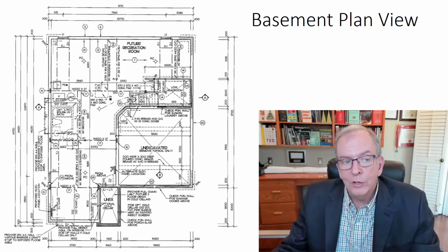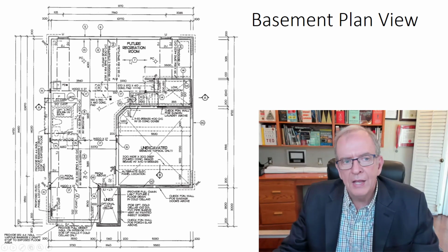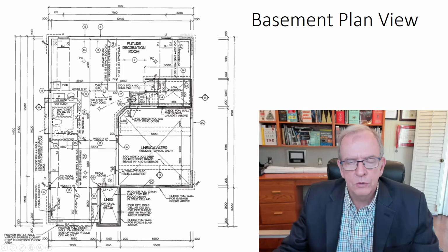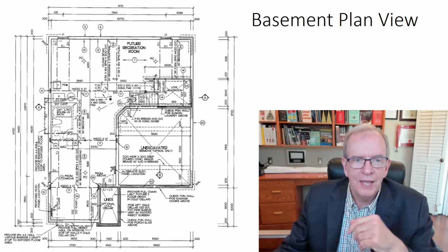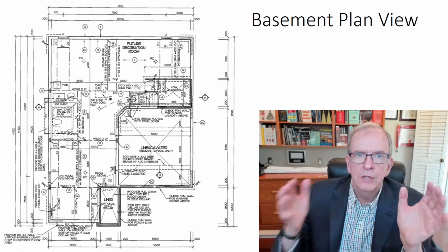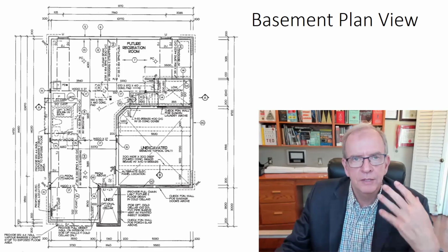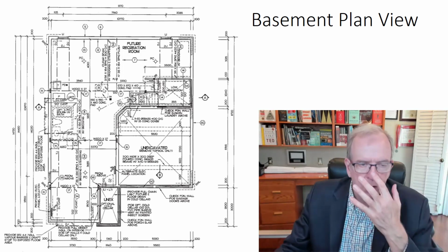More than likely, if you're looking at other drawings, and we'll look at that in some of our other explorations in this construction drawing series, your design would have had an engineered or manufactured joist floor system. In that case, it would just show that it is an engineered joist system, and you would be looking at the manufacturer's shop drawings, which would have an engineer's stamp on it to say it was designed for this particular house.